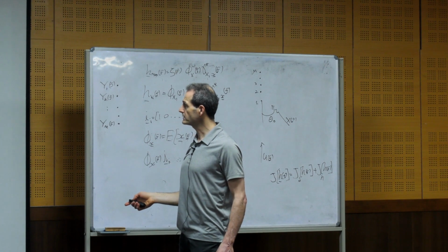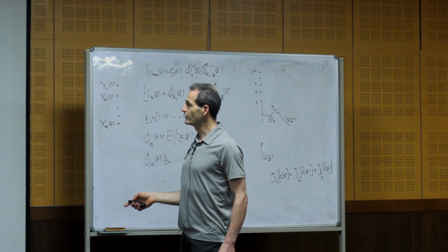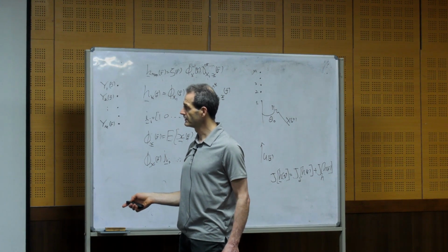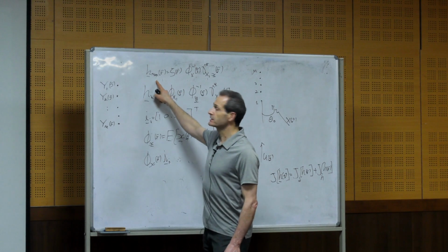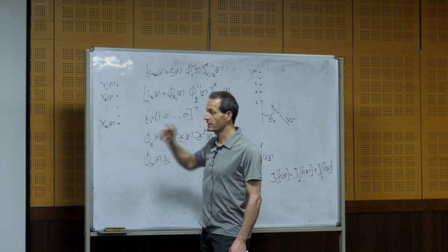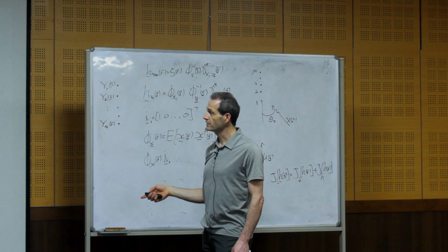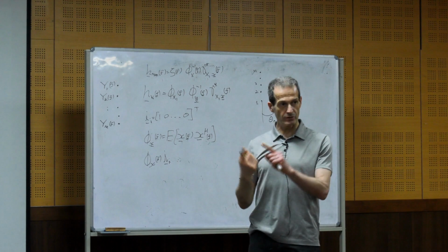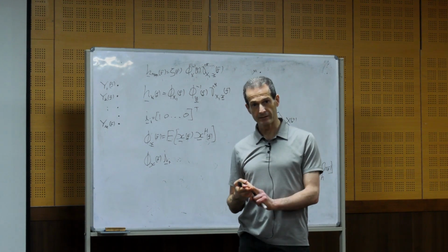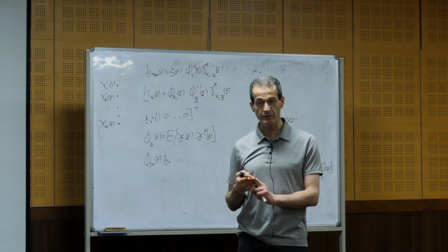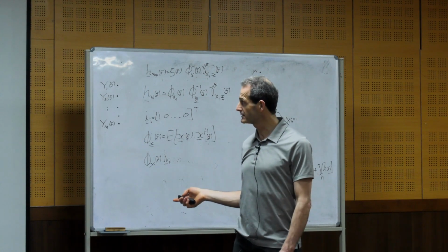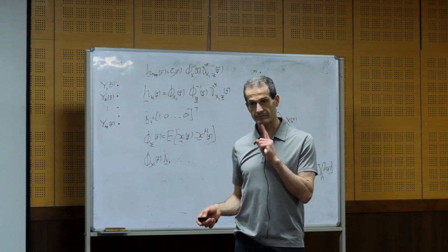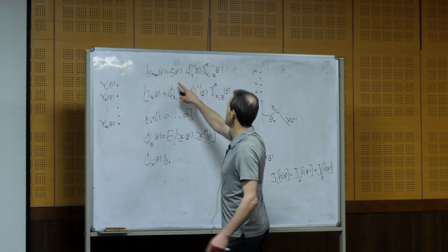So you see we got some relationship between the Wiener filter and the maximum output SNR filter, which means that the Wiener filter not only minimizes the narrowband and the broadband output mean squared error, it also maximizes the narrowband output SNR, because it looks like this.